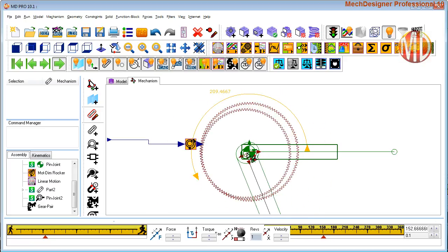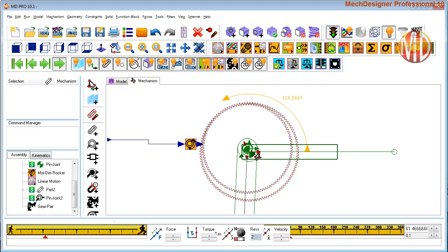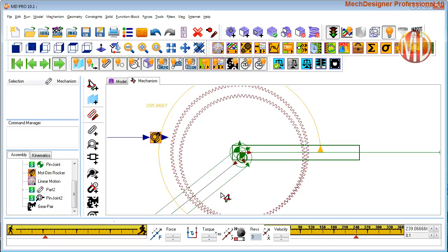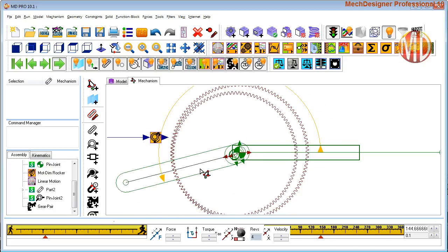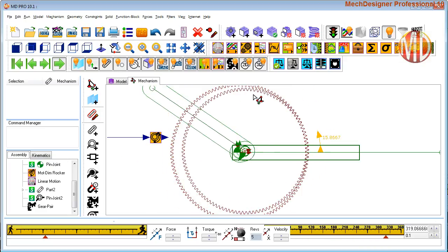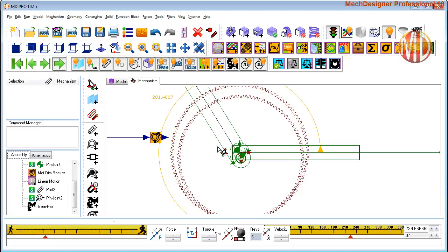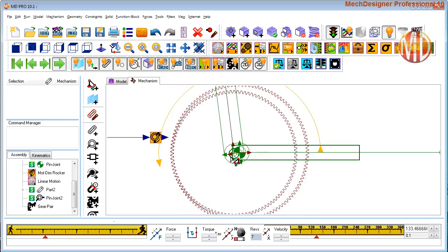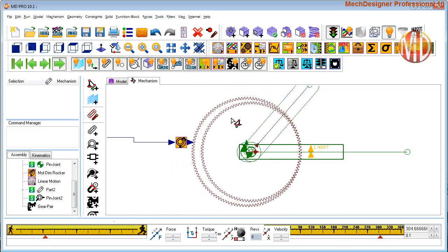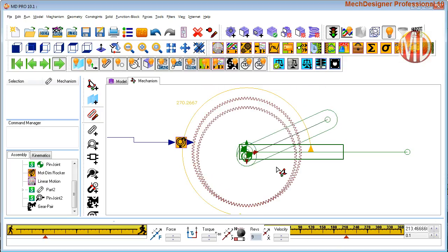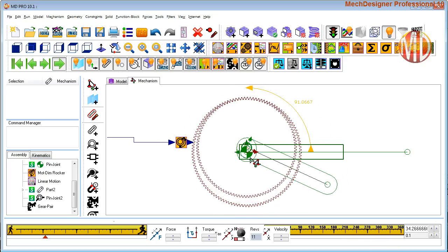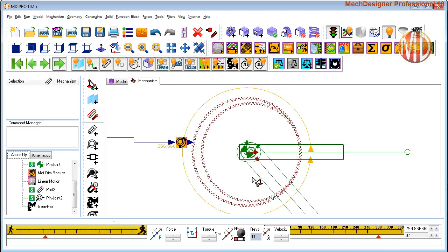there's a small shaft in the middle like a crank. That's really going to be our eccentric pin, and then the output part is rotating slowly. It has a rotating motion, but it also has a wobbling motion by virtue of being on the end of the crank. But the gear itself, if we measured the angular rotation of the gear, then we would find, relative to the crank, it's going at constant velocity.